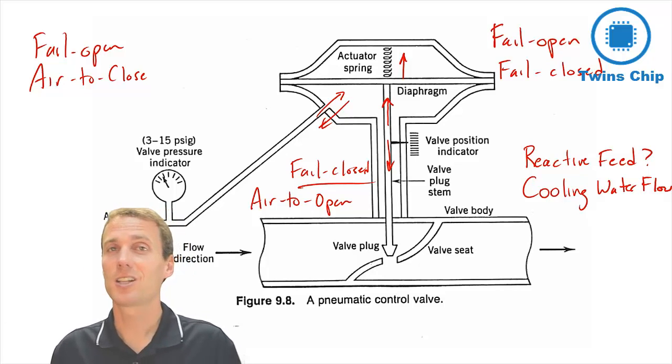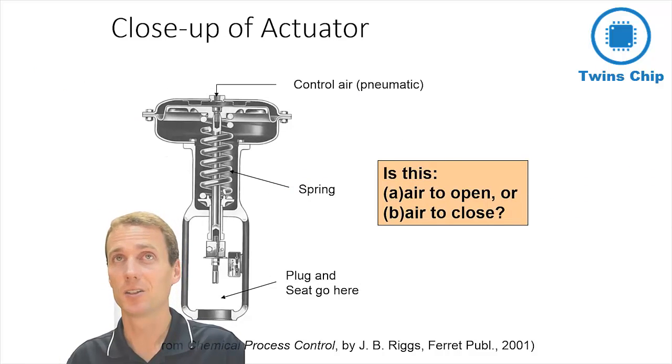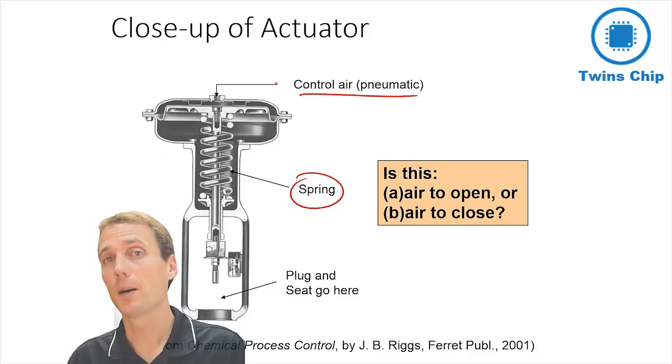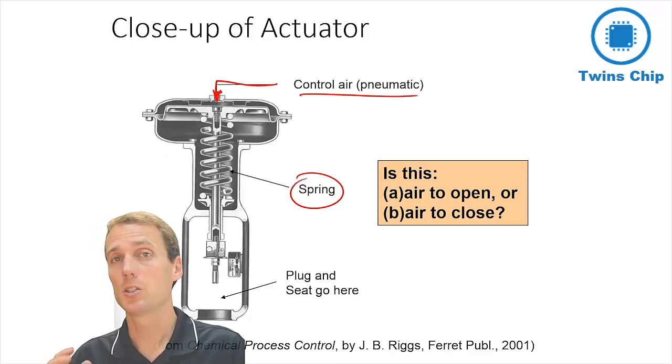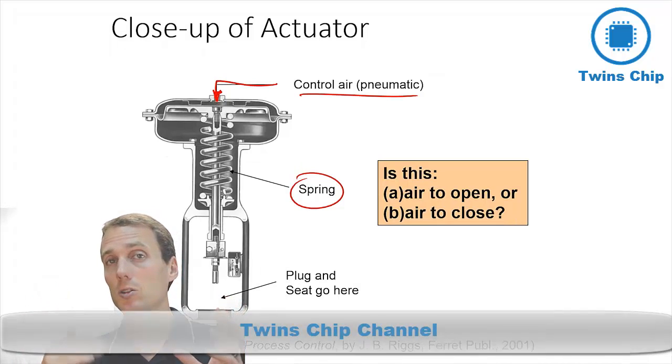Okay, so let's just take a look at another one. Here is one of these diaphragms with the spring actuator. Now the air is coming in from the top. So as you increase the air pressure in the top, then it's going to close the valve.